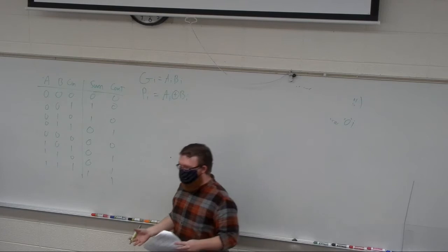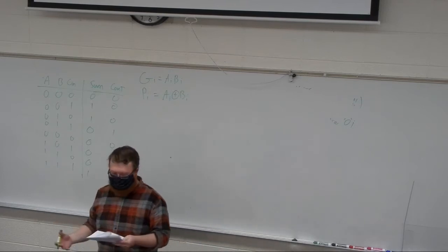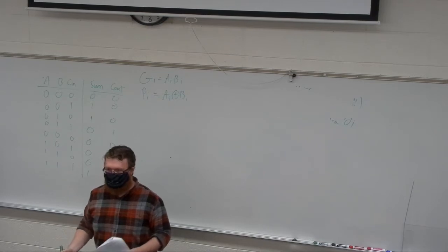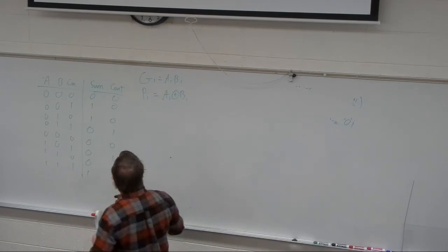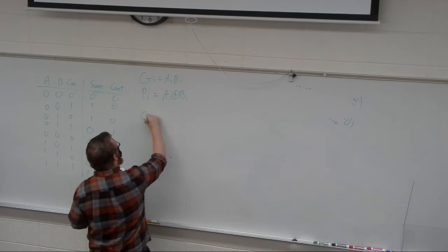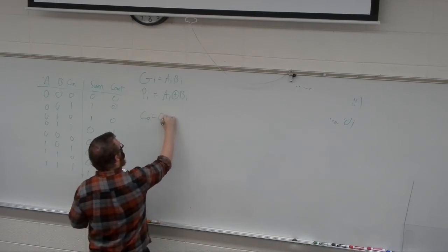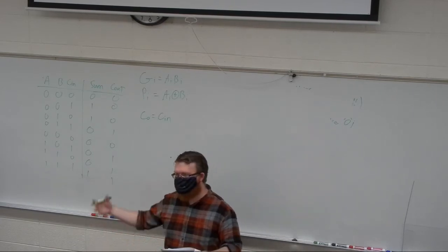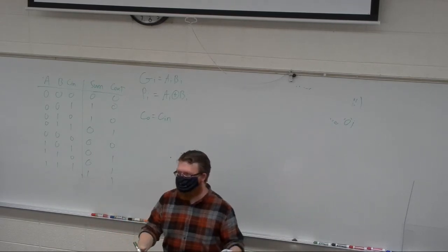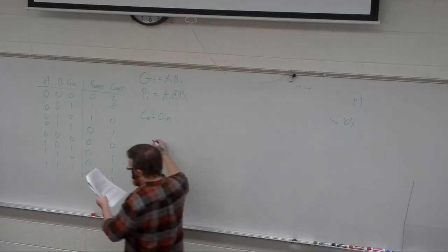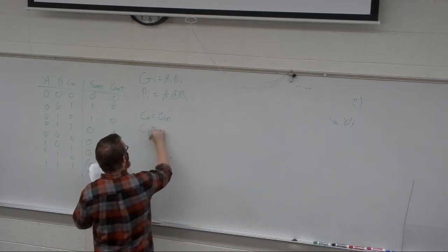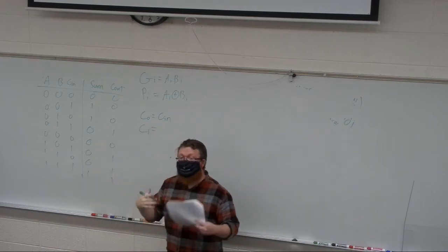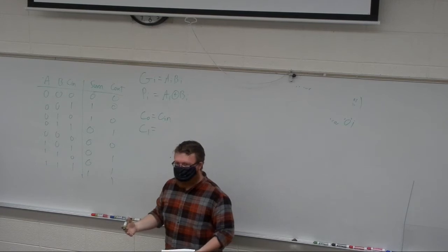So let's consider the first gate and its carry out, right? So the carry out in our first gate is just tied directly to whether we have a carry in or not. And this is what matters if you're stitching multiple of these fast adders together. The carry number 1 then has an additional idea because it might make its own carry, right?